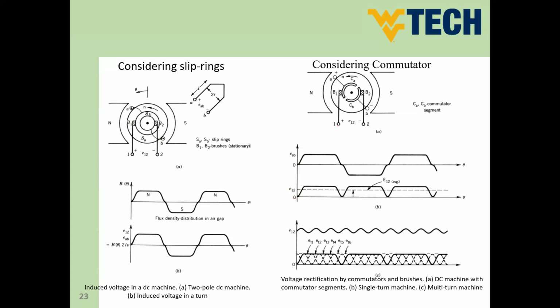And now if we consider just E of one turn, this is going to be the shape. But if you have many turns connected together in series, and everyone has a phase shift for sure because all of them are not going to be in the same slot, in this case, you would have a lot of induced voltages added together. And adding these voltages together, guys, this is going to produce this shape of volt now. So we have few ripples, okay? But this is going to be the summation of many turns together. So having many turns, and then the many turns can produce a coil, and the coils together can be considered a winding of the machine, the armature winding, so we can have smooth DC volt coming from the DC machine. So this is, guys, how the voltage across the windings will be in the DC machine.